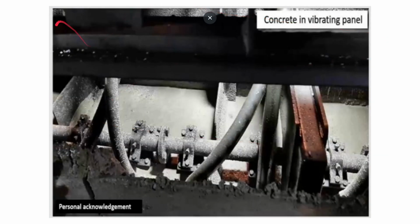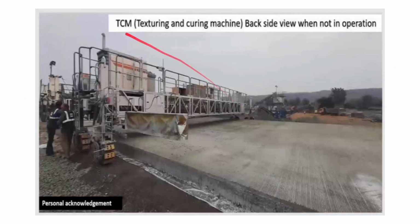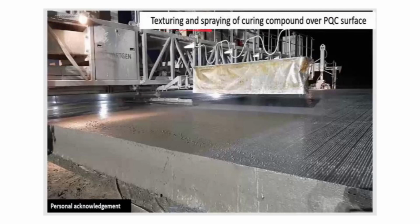This is concrete in a vibrating panel. These are the real site conditions. Here is the mason's trolley. As you can see, after the paver they are trying to perform finishing. Here you can see the texturing and curing machine, TCM, backside view when not in operation. In the construction of roads, this texturing and curing machine is used. Here is texturing and spraying of curing compound over the PQC surface.